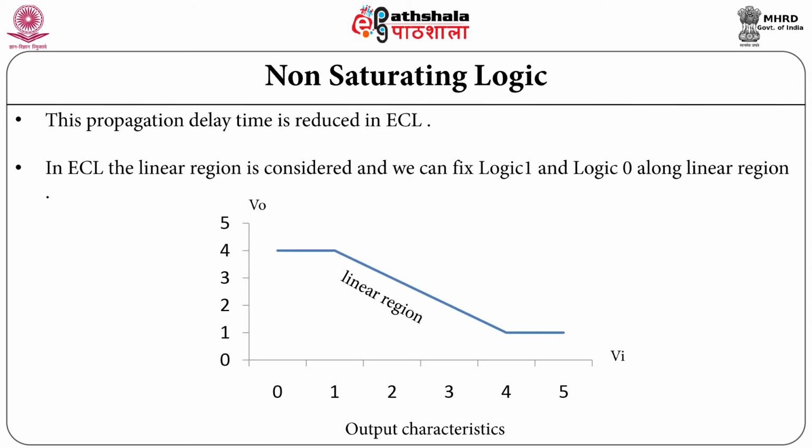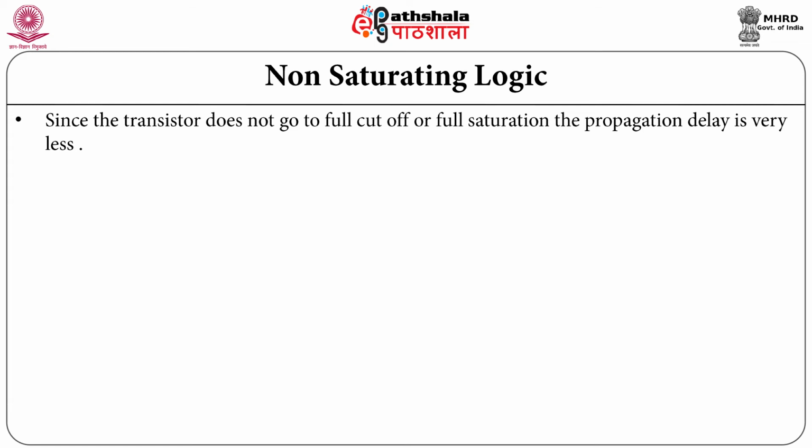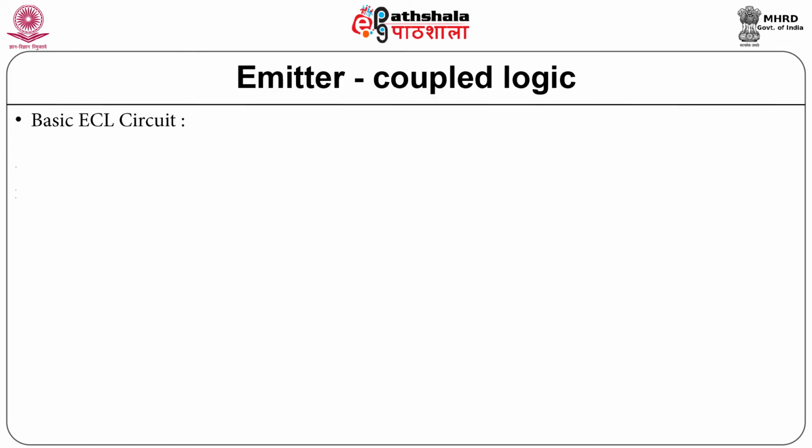In ECL, the linear region is considered and we can fix the logic 1 and logic 0 along this linear region. Since the transistor does not go to full cutoff or full saturation, the propagation delay is very less. Emitter coupled logic, basic ECL circuit.